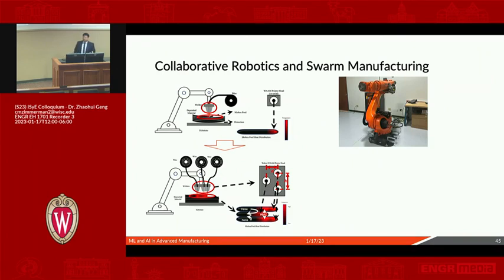We are focusing on wire arc additive manufacturing. The problem we want to tackle is the geometric distortion caused by residual stress. What we do is have three printer heads printing together in an asynchronized fashion so that the heat could compensate each other to lower the cooling rate for each track, and also provide the force to stabilize the process. At the same time, we were talking about introducing ultrasonic vibration to reduce the residual stress in